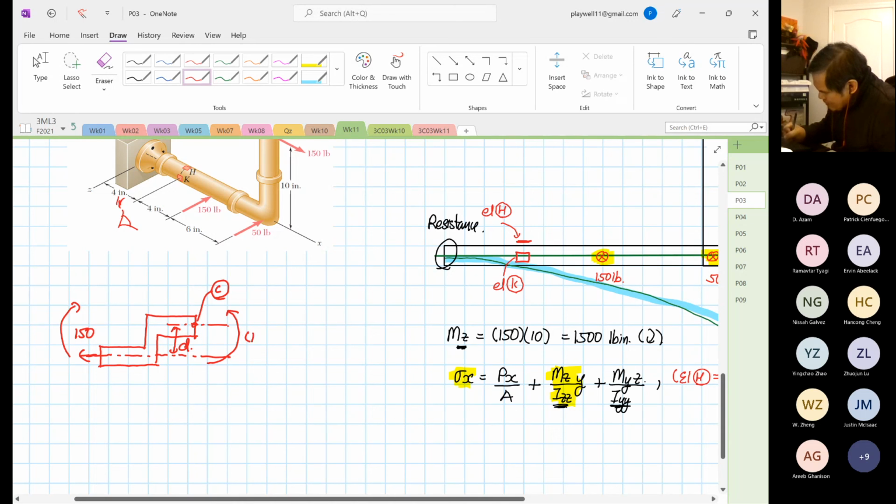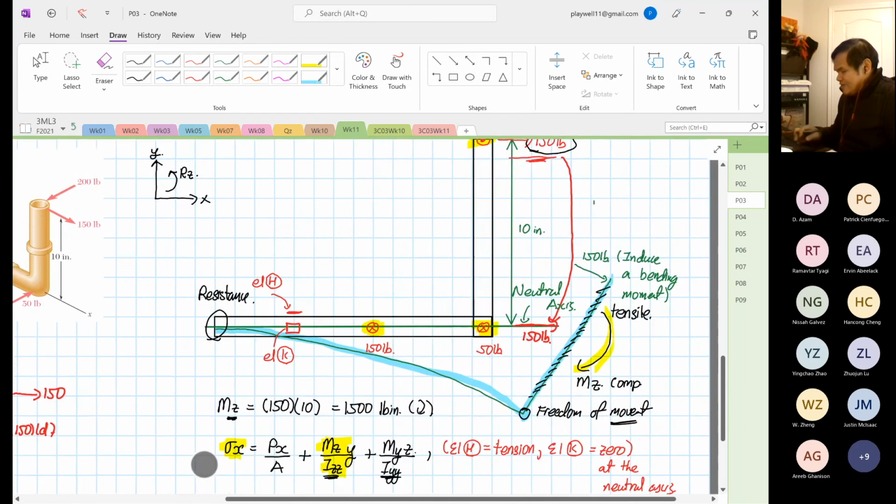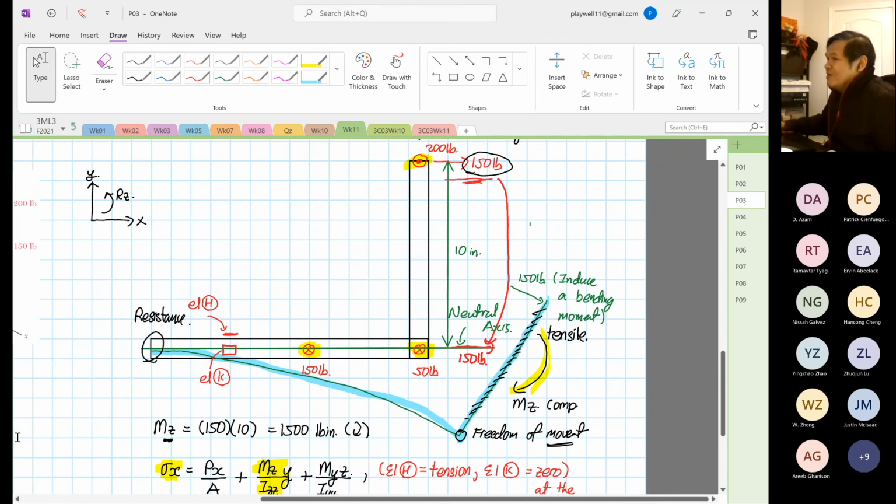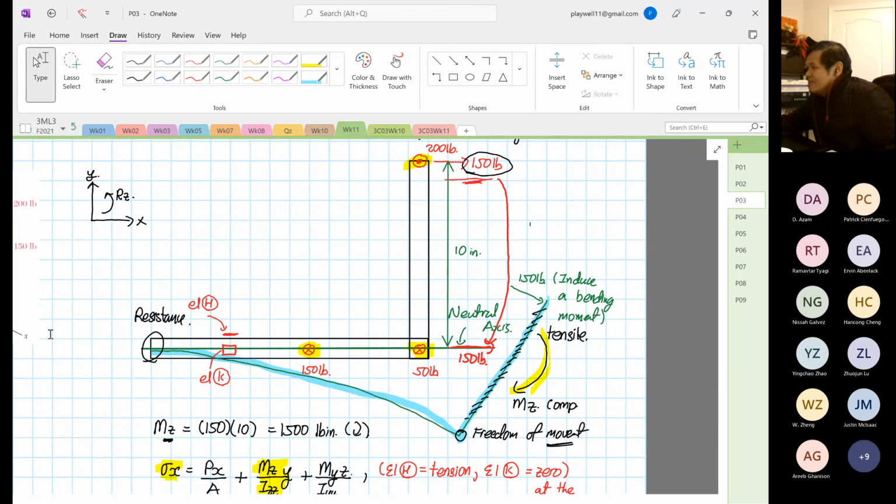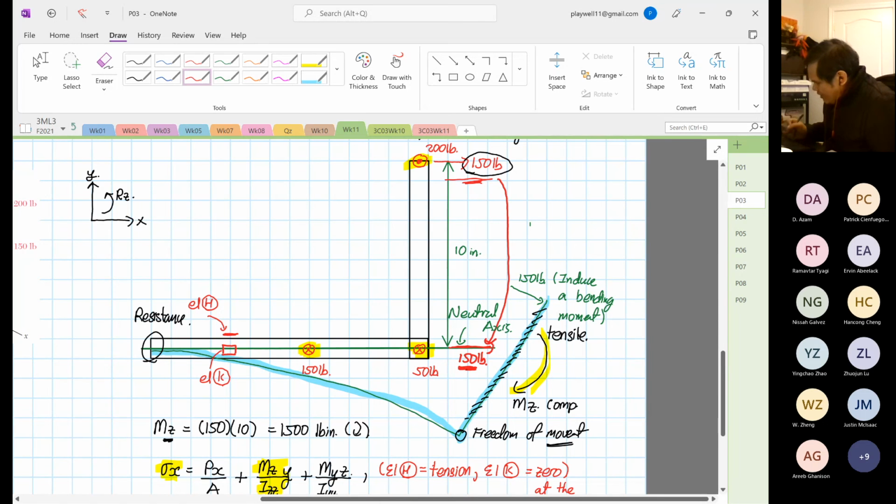What else? Can you remember? Then we also have to incorporate the opposite load down here. So this is 150 multiplied by D, and then we have a corresponding axial load of 150. Yes or no? This is exactly the same. You have seen this before. It's just a matter of recalling. It's not that you have not seen it before. So that's why we have to shift the load 150 over here.